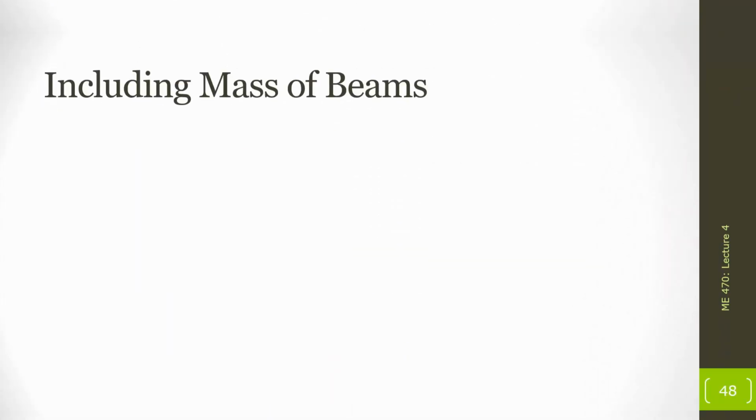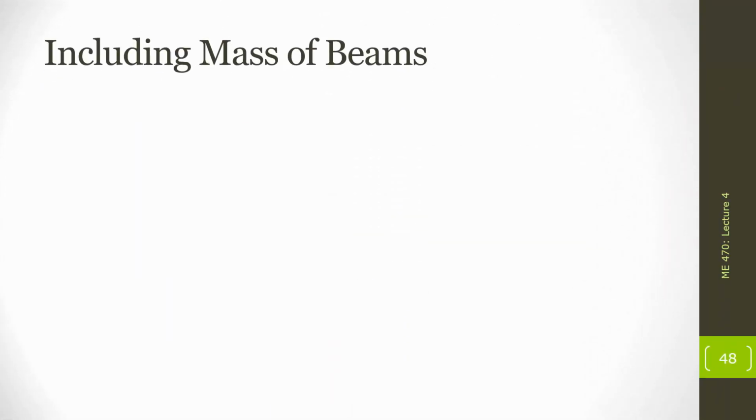So how do we go about including the mass of the beam itself when our beam is a deformable object? Well, as we're about to see, it's not as simple as just finding the center of mass of the beam and putting all of the weight at that point. It's going to have to do with how the beam flexes, because the kinetic energy throughout the beam is not going to be uniform, and that's what just putting everything at the center of mass would be implying.